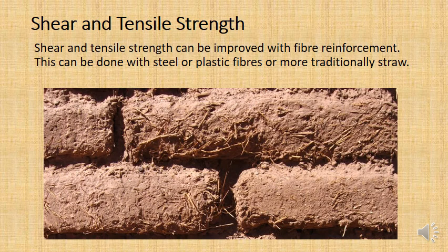Now, it increases the tensile and shear strength of the block itself. It may not necessarily increase the shear or tensile strength of the masonry block wall. Why not? Because it's probably going to break the wall if you strike it or pull it apart in tensile forces along the mortar and not along the blocks. So I'll be talking about how you can improve the shear and tensile strength for masonry walls in a little bit.